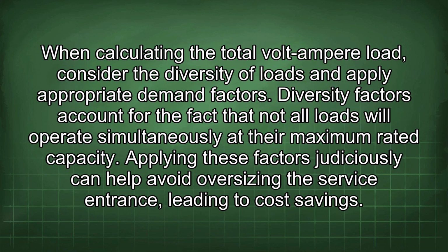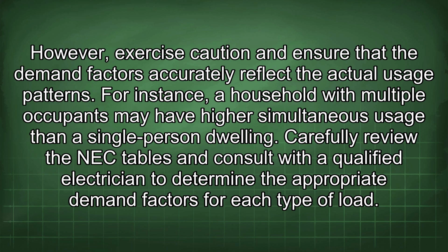When calculating the total volt-ampere load, consider the diversity of loads and apply appropriate demand factors. Diversity factors account for the fact that not all loads will operate simultaneously at their maximum rated capacity. Applying these factors judiciously can help avoid oversizing the service entrance, leading to cost savings. However, exercise caution and ensure that the demand factors accurately reflect the actual usage patterns. For instance, a household with multiple occupants may have higher simultaneous usage than a single-person dwelling.